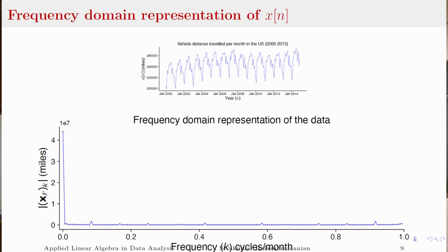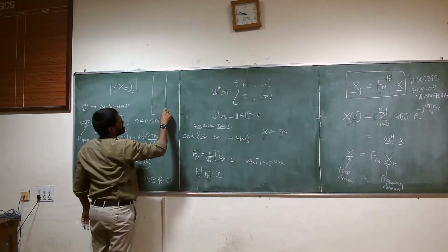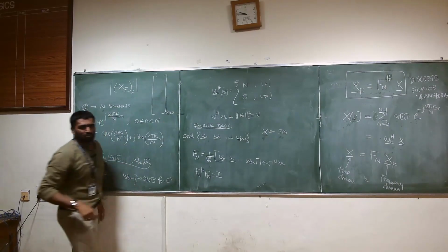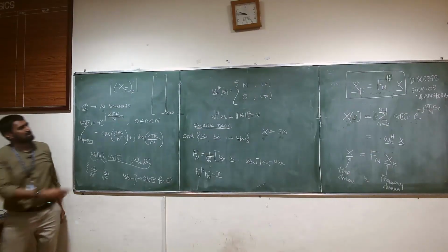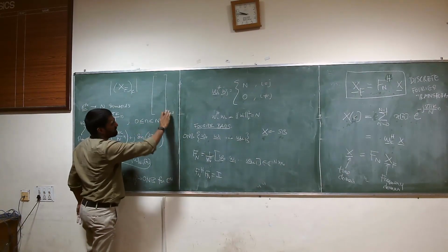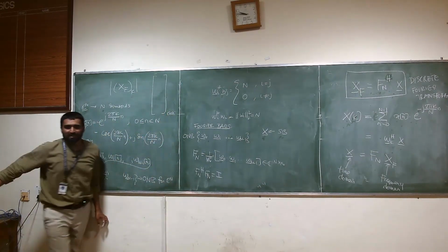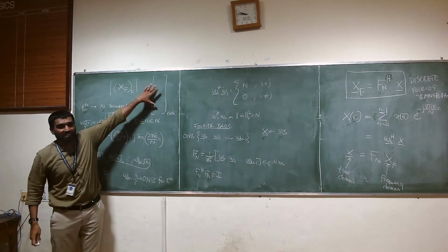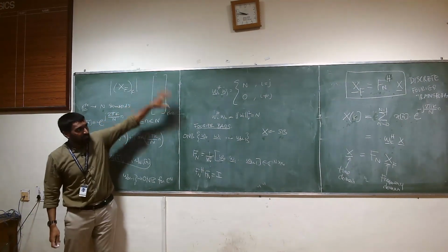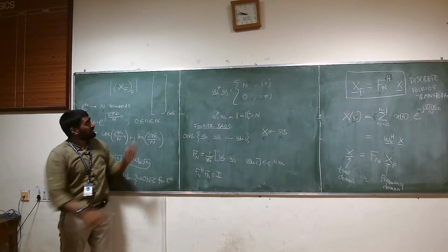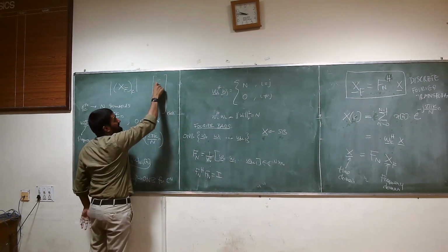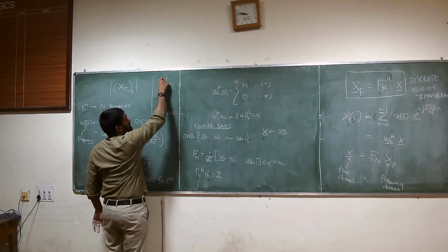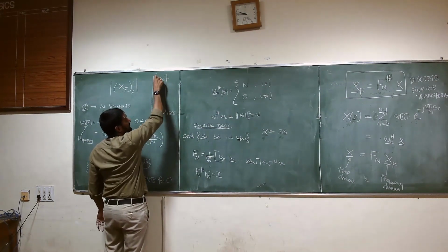So we're dealing with the time domain signal that is, no, it won't be 240. That's 15 years, 12 points. How much is that? 180 points. Okay, so we were dealing with the time domain signal that had 180 points. If you do the Fourier decomposition, you get another vector which has 180 points, and each of these values corresponds to a different frequency.